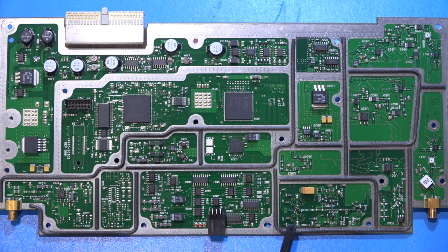So here at the bottom is our VCO, and you can identify it by the groups of varactors, which are made of diodes in reverse bias, and a single transistor in the middle. You can tune this, and it has a really wide tuning range of almost a factor of 2, from 500 MHz to a gigahertz. So the output of that is then taken forward.